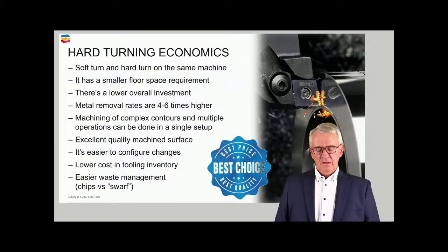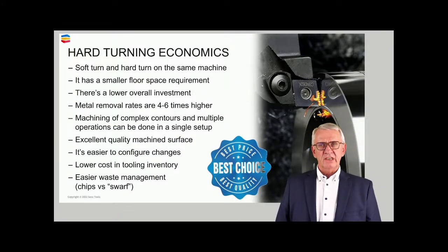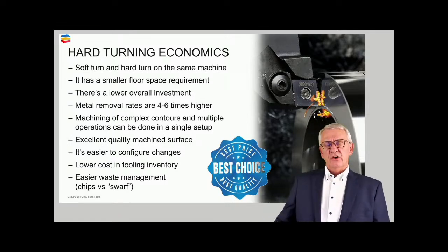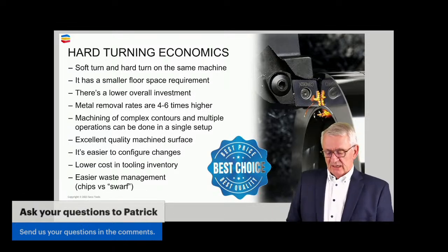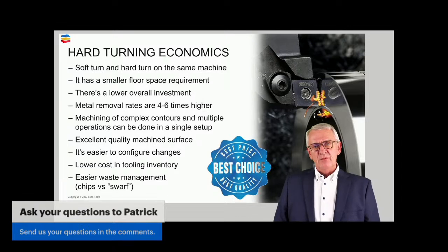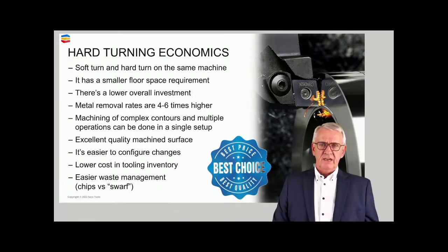In general, one could say that, especially in comparison with grinding, hard turning economics are making hard turning, milling, drilling, mainly with PCBN cutting materials, the best choice in hard workpiece materials. I'm not going to read every single sentence here on this slide, but nearly every aspect, every element in this process is in favor of hard machining over grinding, which makes hard turning the better alternative.